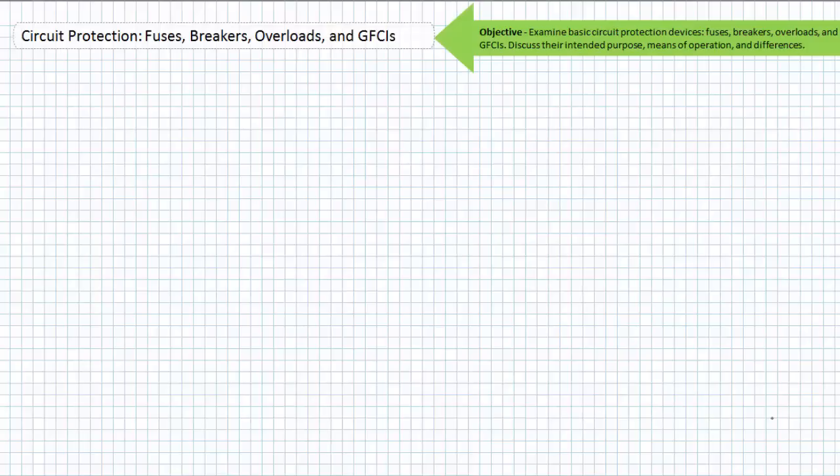This being said, a blown fuse is a non-reusable component. Following safe work procedures, the system must be locked out and tagged out, the error that caused the high current removed, and the old fuse must be removed and replaced with a new one if this system is to operate again. In short, replacement requires intervention, and it is sometimes not a simple process.